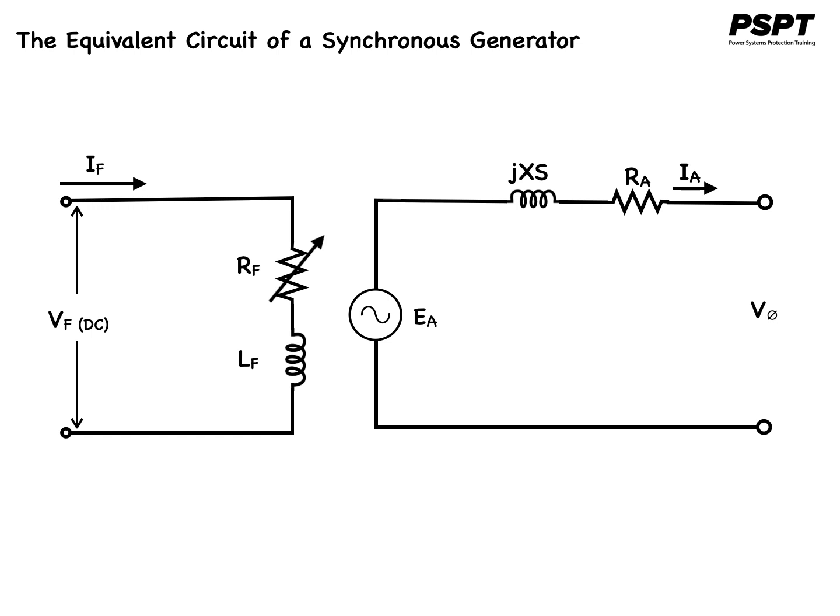One important fact must be kept in mind when the per phase equivalent circuit is used. The three phases have the same voltages and current only when the loads attached to them are balanced. If the generator's loads are not balanced, more sophisticated techniques are required for analysis. These techniques are beyond the scope of this course.